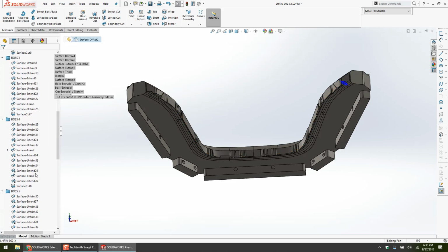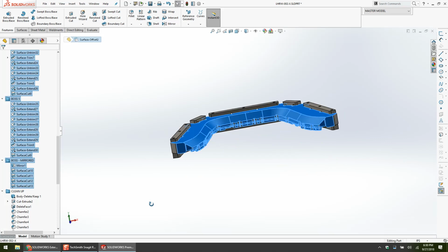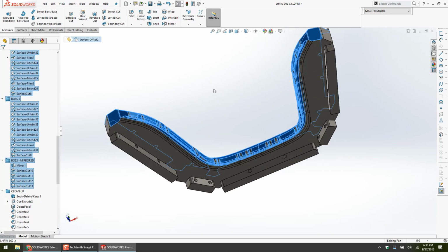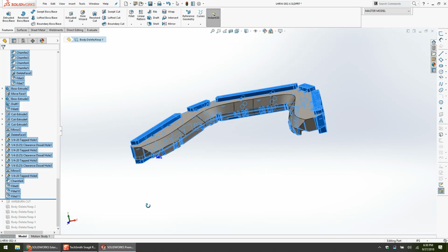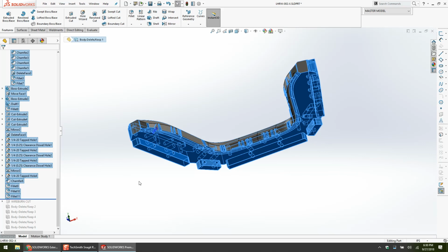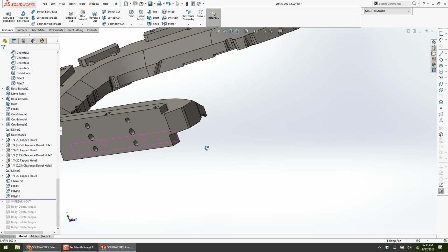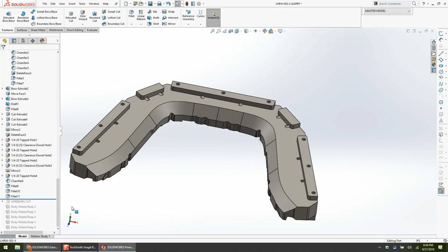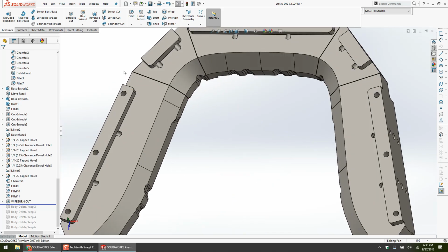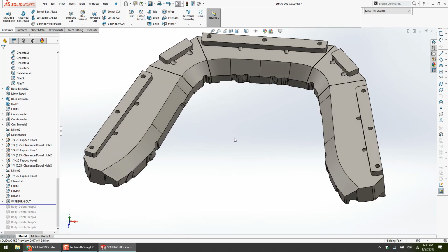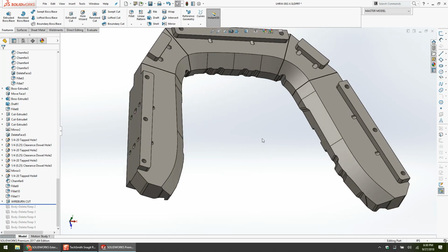Most of this is surfacing, right? So from here to here is pretty much surfacing, just to get all the contours and to manage everything that I'm trying to accomplish. Then after that, we start cleaning up, and these are the solid features, the base extrude, and then up to the surface, and then the trim, and then we put in the holes. And the very, very last thing that I do here is my wire burn cut that puts in my cuts so that my 5 pieces can come together. So all of these would touch in perfect reality except for the 10 or 15 thousandths wire burn slot. And I can buy a single block of steel and cut this much more efficiently in the CNC, wire burn it, and then put all my holes in.